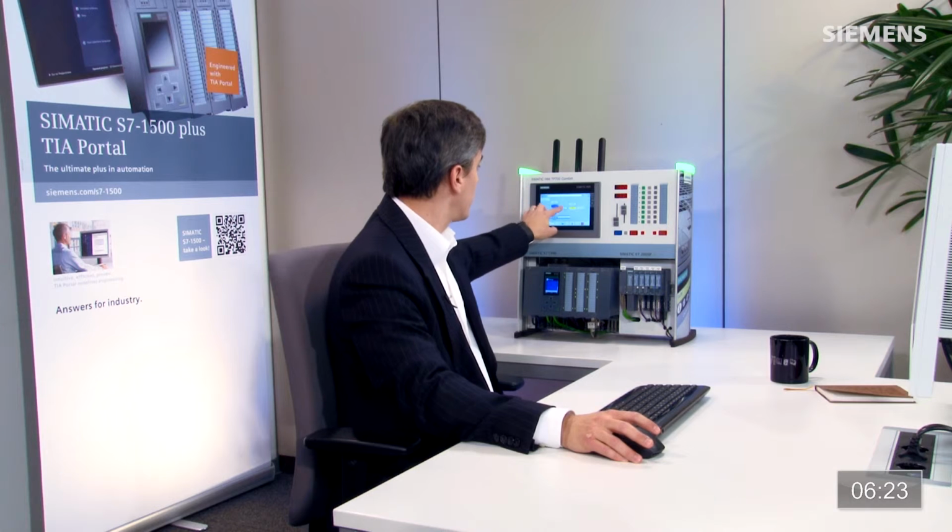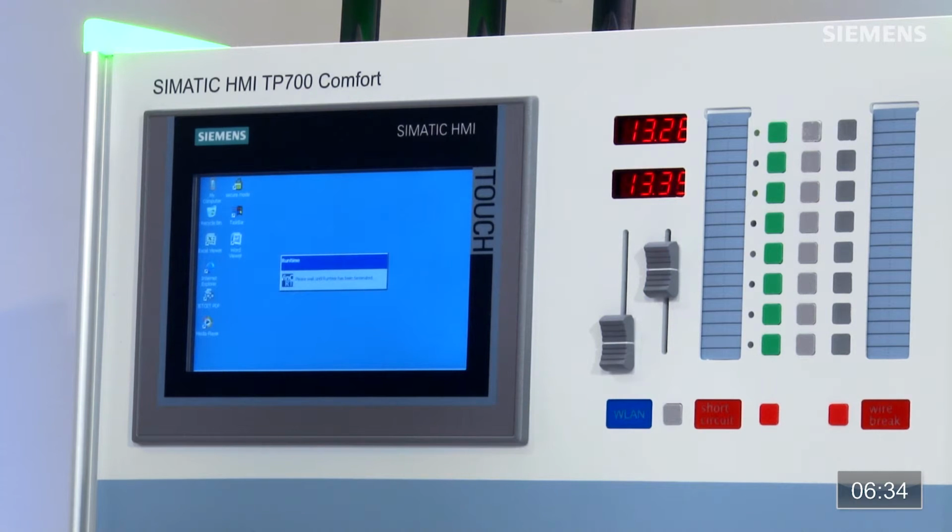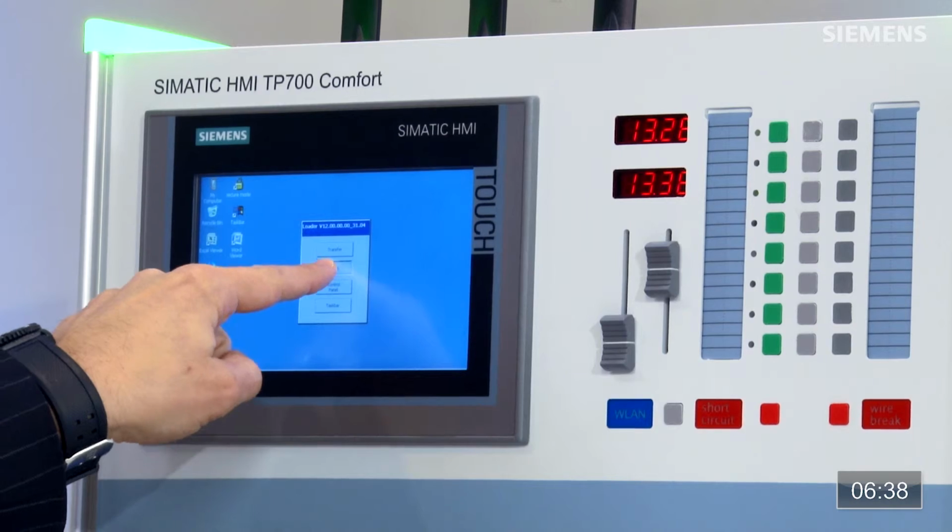However, I still have complete control from the panel because I have an existing connection. Until I reestablish connection, does it actually blow it up? Well, let me actually shut down the runtime. That's the easiest way for me to do this. Once the runtime is completely shut down, it'll give us the ability to restart. Once I do restart, he's actually going to try to reconnect to a protected CPU at Level 4.